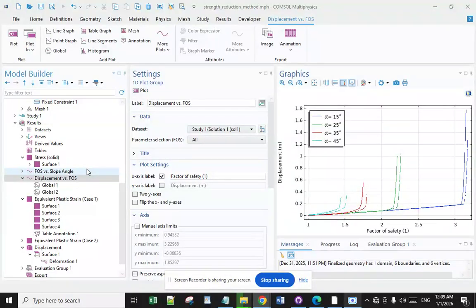A margin of 0 would mean the part would pass with a safety factor of 3. If the margin is less than 0 in this definition, although the part will not necessarily fail, the design requirement has not been met. A convenience of this usage is that for all applications, a margin of 0 or higher is passing. One doesn't need to know application details or compare against requirements. Just glancing at the margin calculation tells whether the design passes or not.